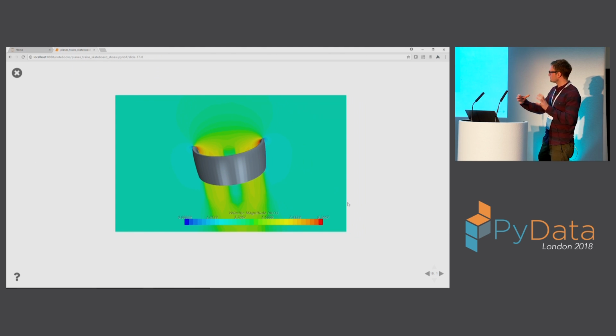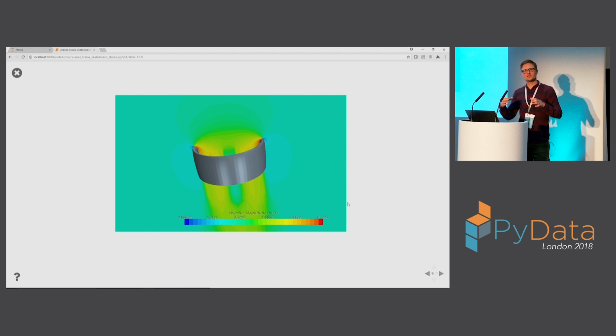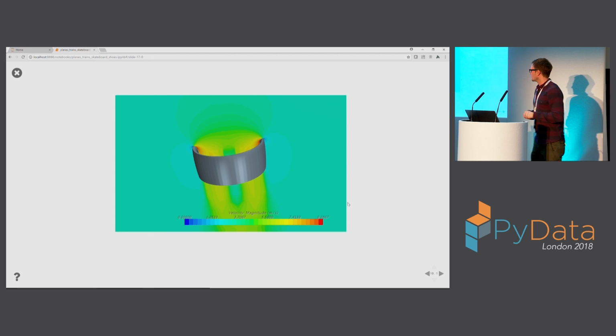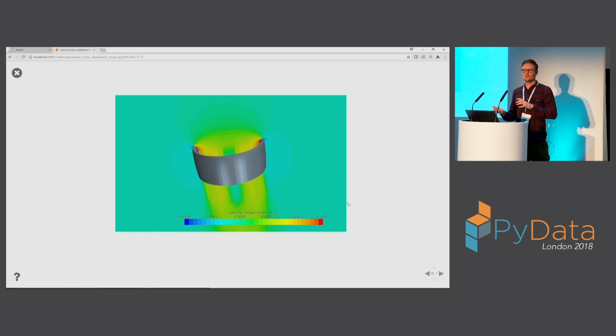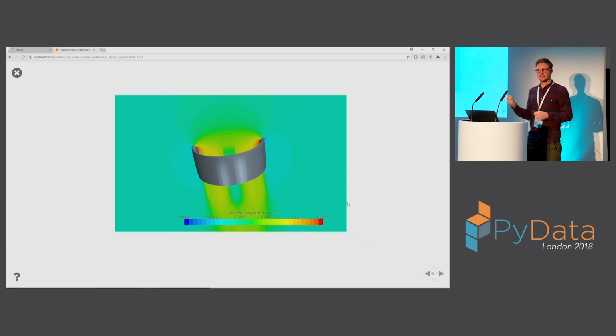Okay, so this is that ducted fan that goes around the drone propeller. So like I said, when we introduce this new component to the drone, we're going to impact the performance of the drone. We're adding weight. You're going to have to increase the power requirements. There's a whole bunch of stuff you need to start thinking about. So you need to design this thing quite carefully.